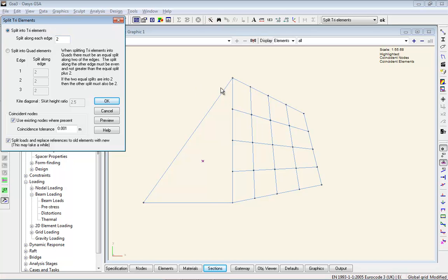And we can use the split under 4 elements on the edge, and that splits the triangles into more triangles, or you can split the triangles into quads, and maybe adjust the diagonal option, which is going to be generally good apart from this dubious element in this.